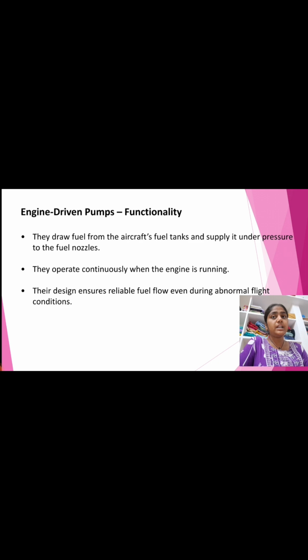The combined operation of boost, transfer, and engine driven pumps ensures a smooth and efficient fuel supply system. Boost pumps provide the initial pressure required to feed the system. Transfer pumps manage fuel distribution within the aircraft, and engine driven pumps deliver fuel to the engine at the required pressure and flow rate. This coordinated operation helps in maintaining engine performance and preventing fuel starvation under all flight conditions.